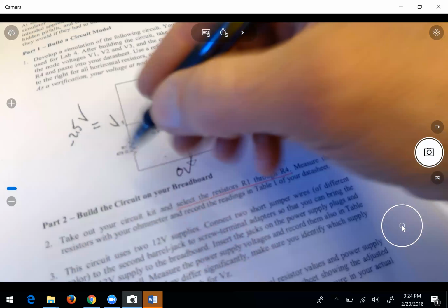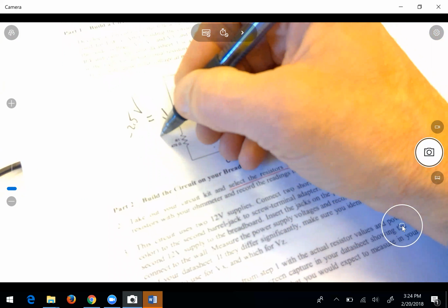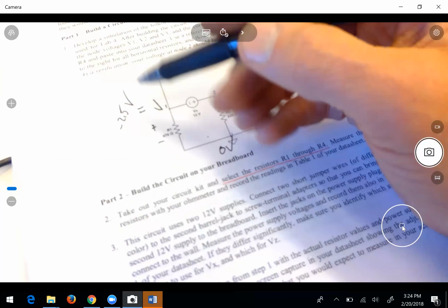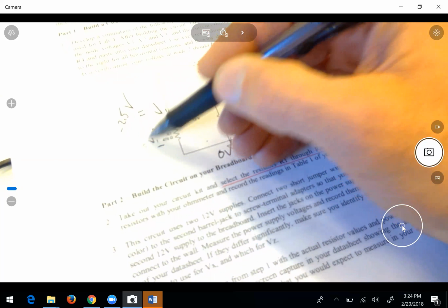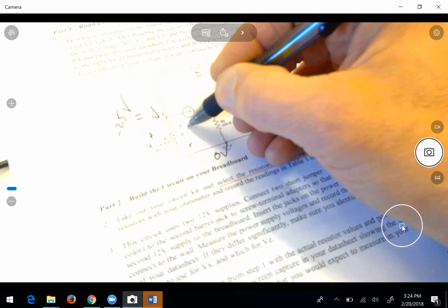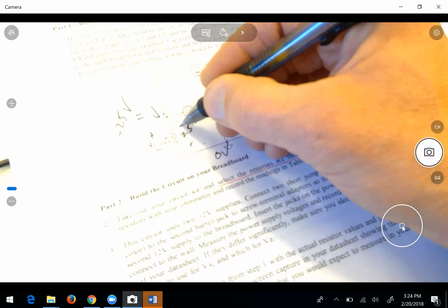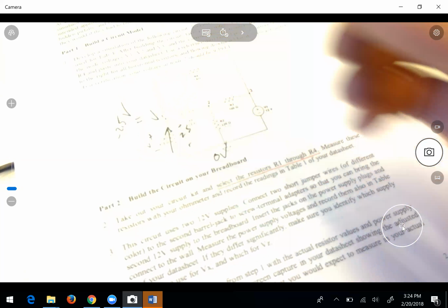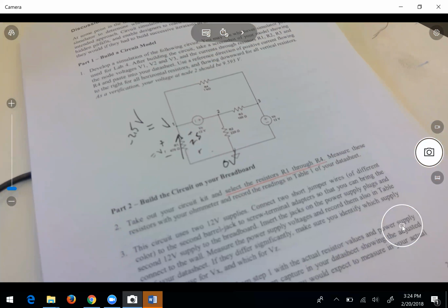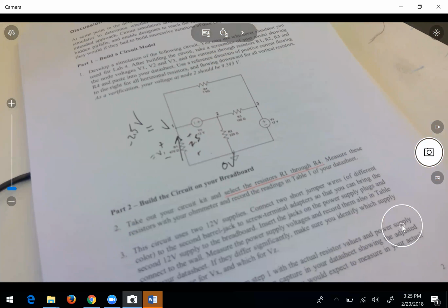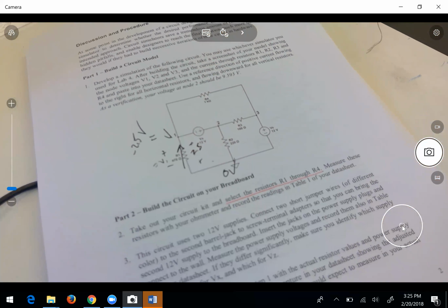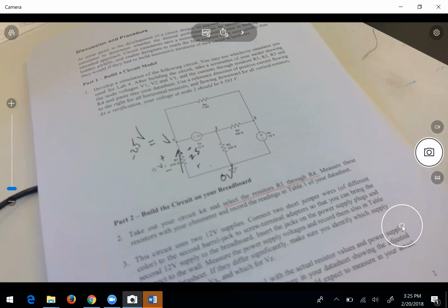So, but what's the voltage drop? If I asked you what is the voltage drop across this resistor, it is negative. Yeah, it's negative. That's the same as V1, right? Well, you've got a 2.5 volt drop this way, right? So which way is current going through the resistor? It's going up. And the power is I squared times R, or V1 times I, using the correct sign convention. I times V is power. So it is dissipating power.